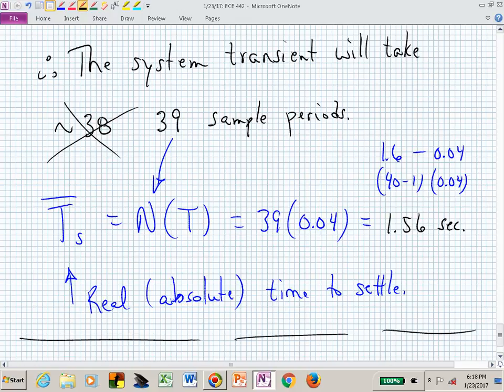So if you didn't need to speed up your system and you had a continuous time system matrix, you would look at its fastest eigenvalue and say, oh, I need to sample 30 times that. Meaning if it had an eigenvalue that was the fastest at minus 10, now you need to sample 30 times 10, or 300 radians per second. That would be your omega sub s, and you can now back that out to find what T is. But your system representation in the discrete time is going to definitely depend on that capital T.